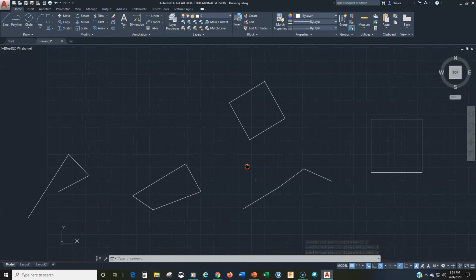All right. So there we have our 3 top drawing methods: relative Cartesian coordinates, relative polar coordinates, and direct distance entry using dynamic input and polar tracking. All right. We also looked at the undo command and things that could go wrong if we forget the @ symbol and how to fix that. Let's finish up right now by saving this drawing file. We'll also prepare it for plotting by printing it as a PDF file, so that you're ready to submit it if you are going to submit this drawing file. This is not an assigned drawing file, but you can still practice that.